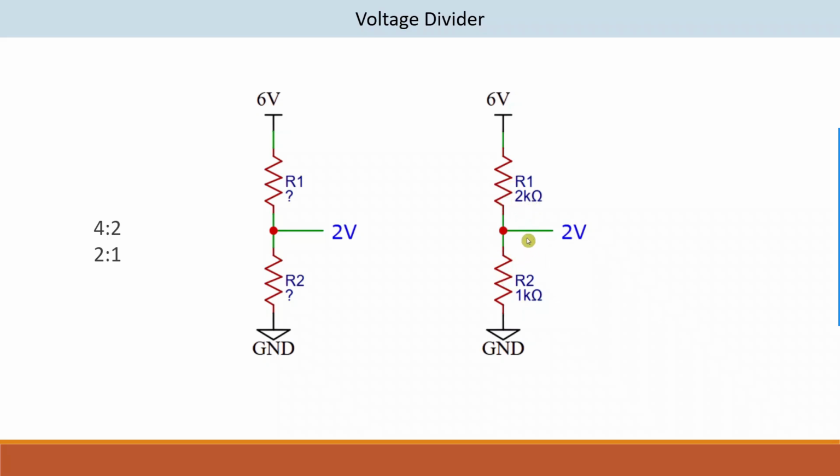If you need a higher current at the output side, then you can use lower resistor values. So it depends on your output circuit, on what you are going to connect at the output. If you are going to connect an op-amp circuit at the output side, then you can use higher resistor values, because an op-amp does not need much current.